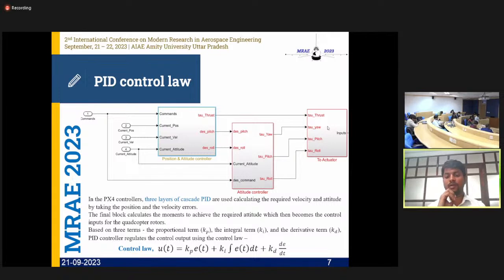So why is the attitude controller important? When we give any maneuver, we give it in the form of pitch, roll, and yaw, and the response of your system or plant model depends on how quickly it accepts your command values, and how quickly the attitude part reaches those values. So basically, it makes the attitude control a very crucial part of controlling the quadcopter.